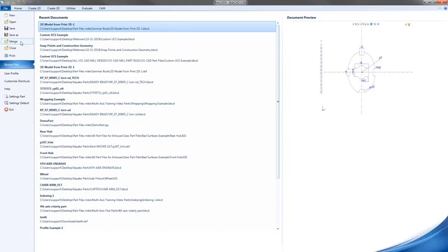What's really cool about this is when you merge a file in, you can draw an entire part file. It might have a really large size to it, and then if you don't want to lose any layers or anything else that you've done, you can merge a file into a nice blank window. It'll drop the entire CAD tree, which means it shrinks the file, whatever the amount that CAD tree had to it. So it's going to make this file a whole lot smaller, a lot easier to work with, and you're going to have a nice fresh save with it. The other thing, when you do merge, it does not bring in toolpath at all. It just brings in the part and doesn't put any toolpath on the screen.